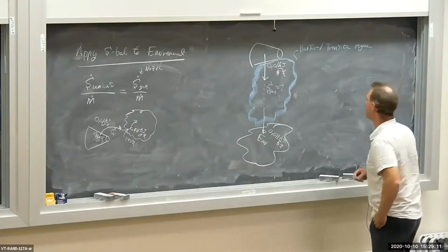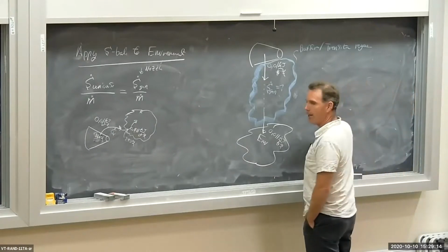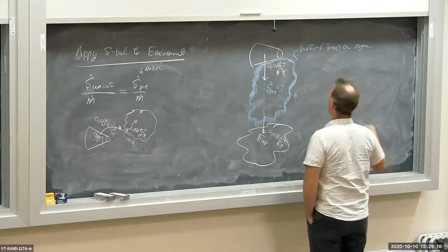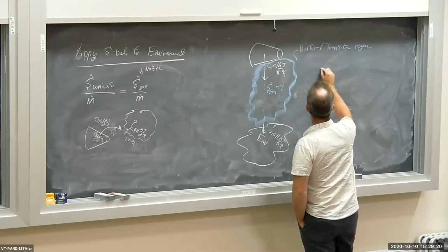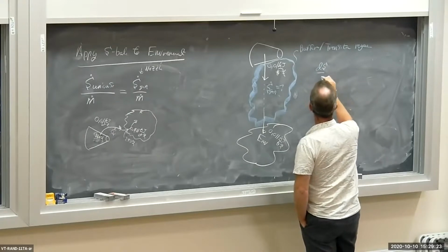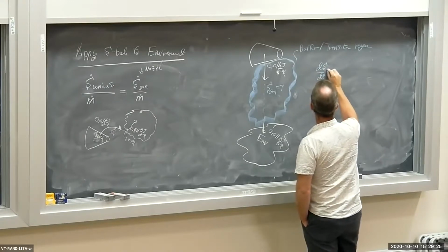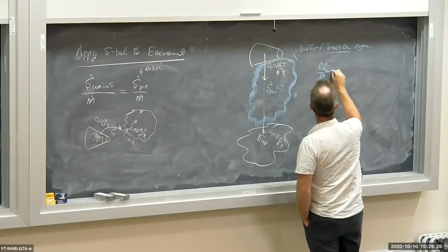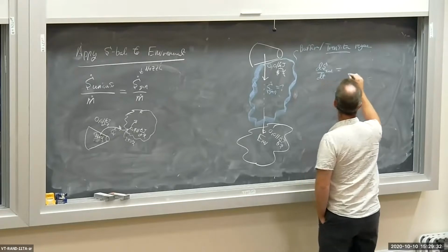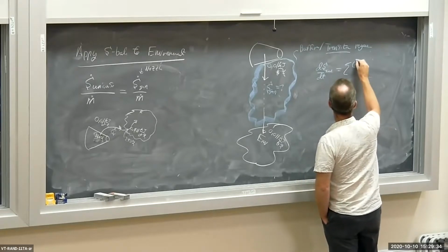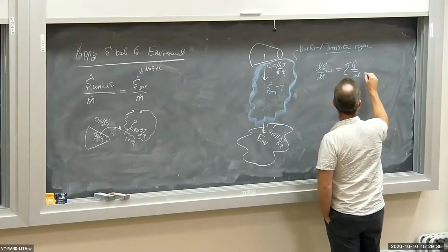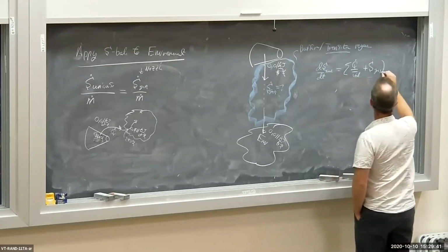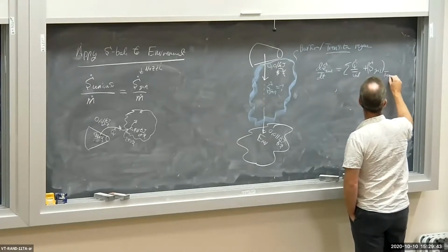Well, let's apply the entropy balance to the buffer region. dS/dt for my transition or buffer region is equal to the sum of the heat transfers over the interaction temperature plus S dot gen in my transition region.